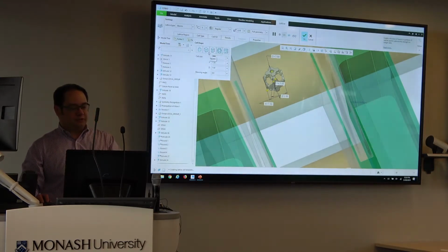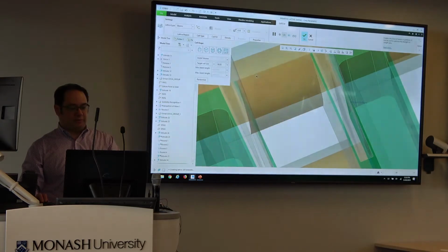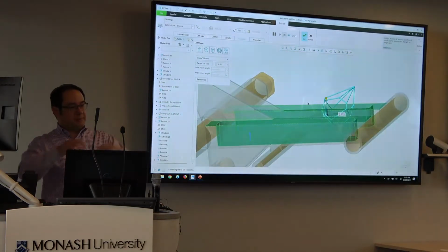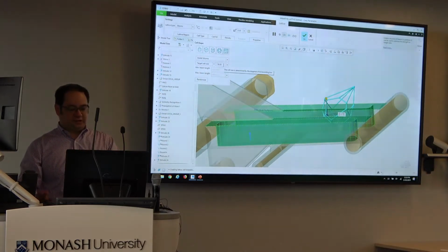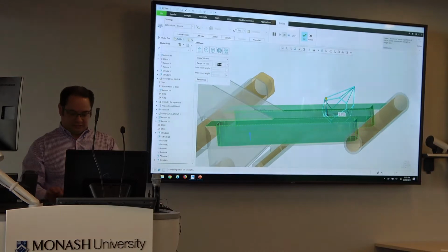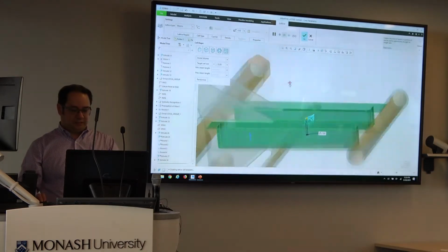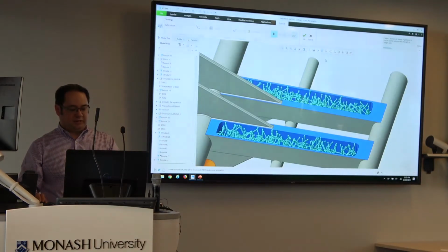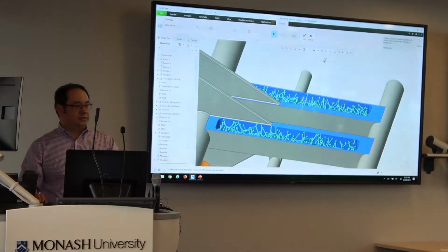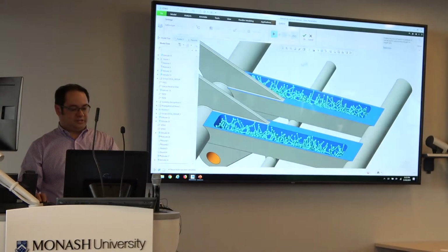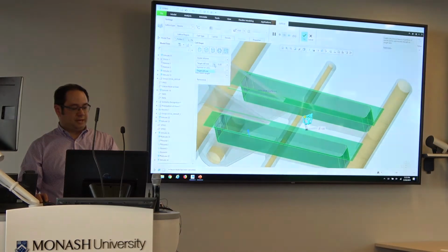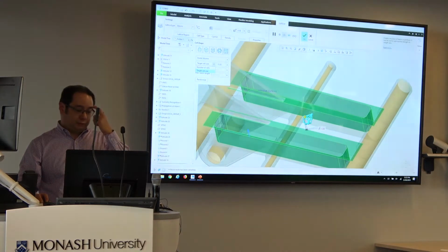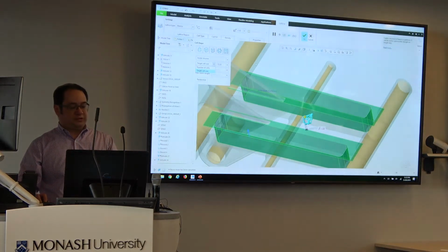So what's new now is the new stochastic option. This is creating a more randomized kind of shape. It's using beam elements. We can say target cell size. So there's one cell of that. Let's drop that down to like 15, like so. What that's going to give us is this kind of irregular fill inside that area. So we can say that based on a cell size, or we could say it based on a number of cells that we want to have inside it. We also have the option there to randomize that as well. So that's the new stochastic option.